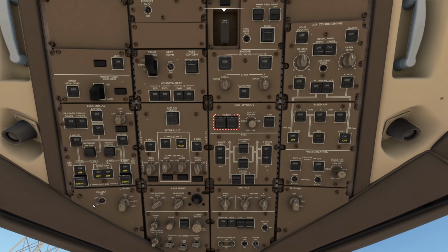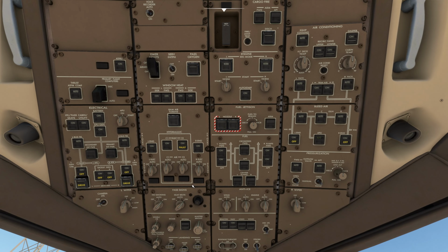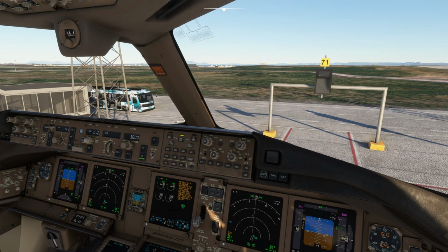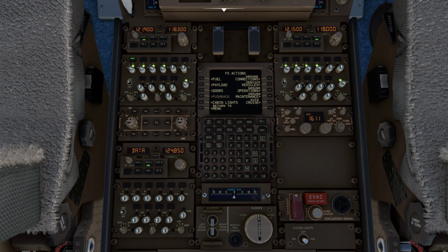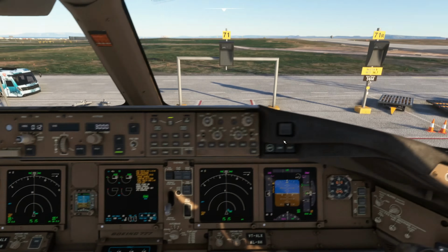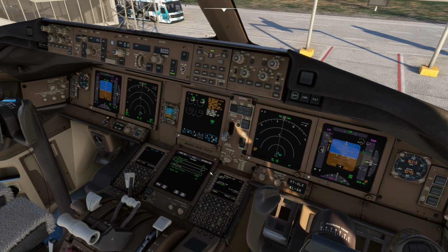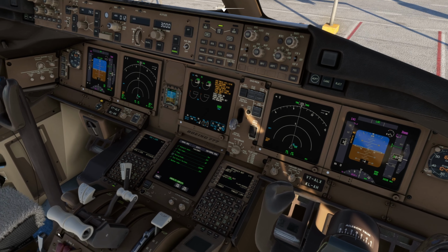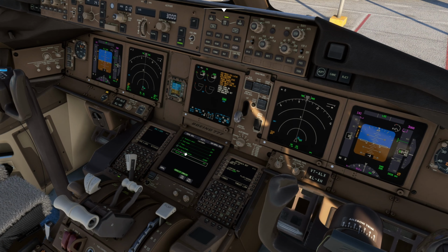Okay, now the before shutdown procedure. So we'll start from here. Off, fuel pumps off, beacon off, and the FDs off, transponder to standby, squawk 2000. Yes, before shutdown checklist, parking brake is set as of now because the chokes are not set yet. So shutdown checklist complete.